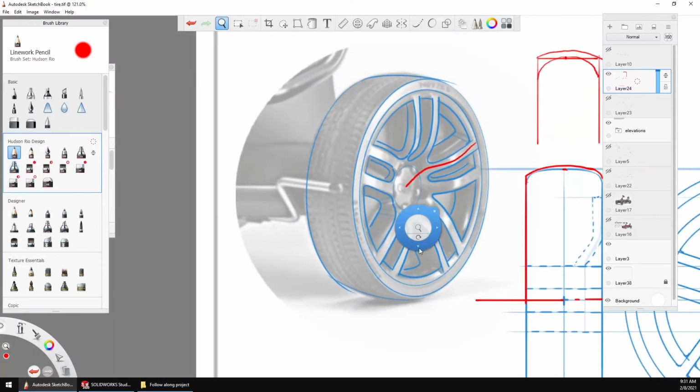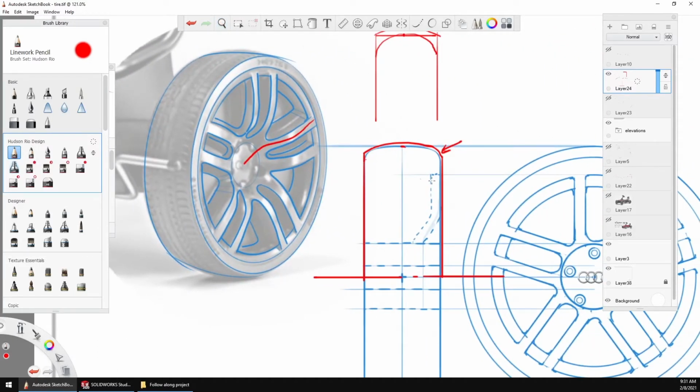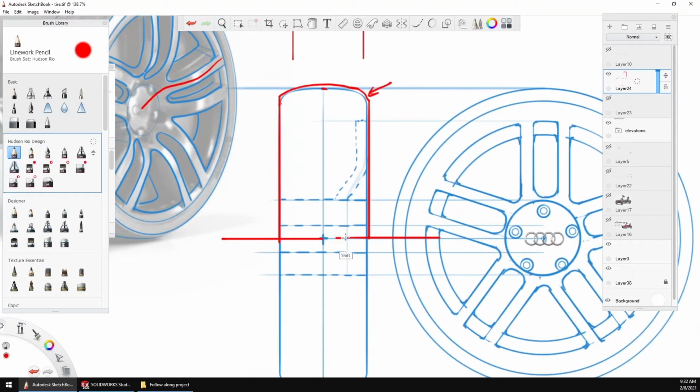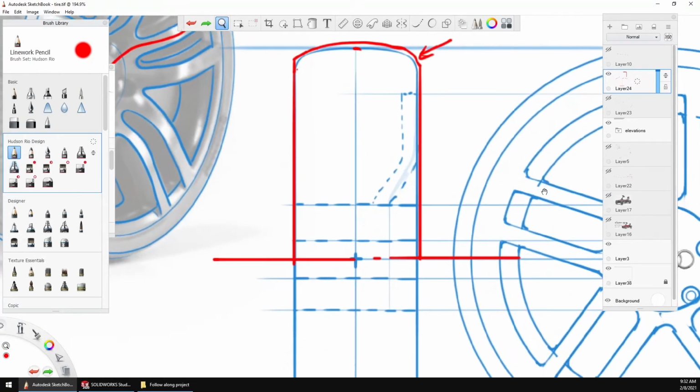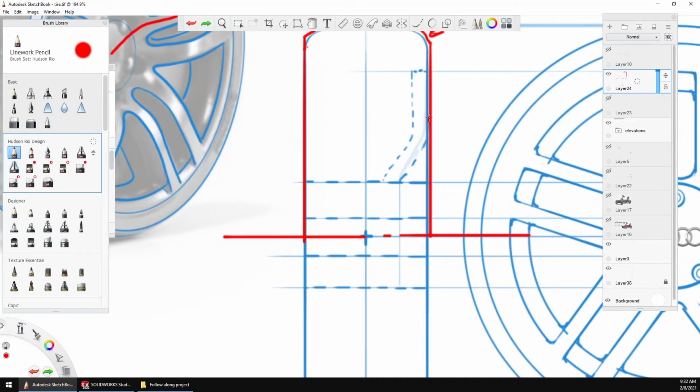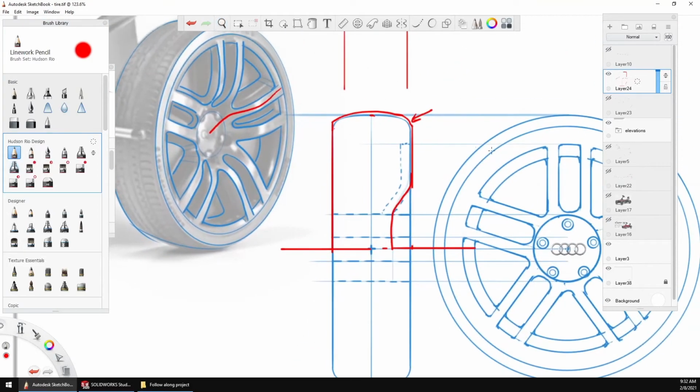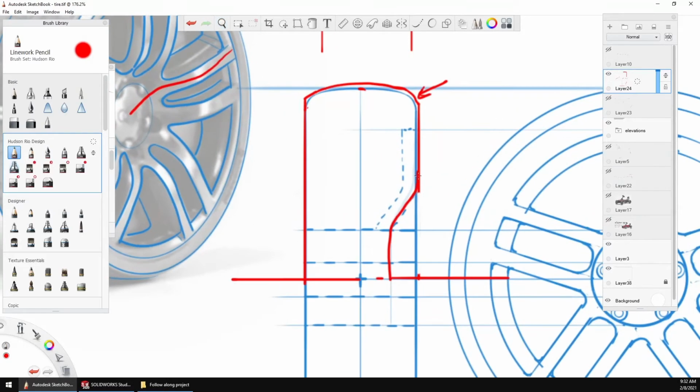So if I look at that, I could sit there and say, okay, well, after I revolve this, I could do an extrude cut to get that bottom area removed. Now, it feels like that is an added step. So what if I was to simply do my revolve in a 2D profile and get that shape in there right off the bat? That's going to give me that contour that I've got. It's going to allow me to have my larger radius.